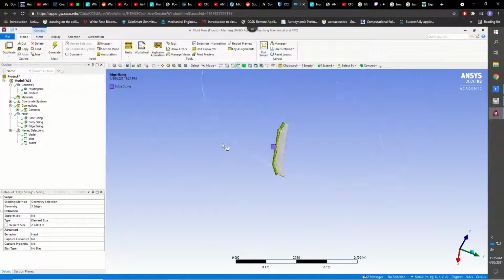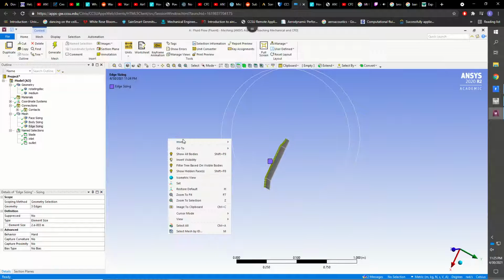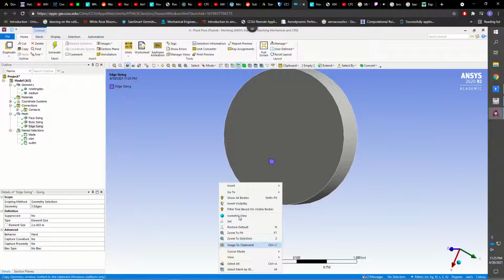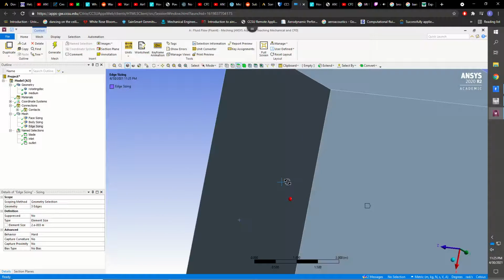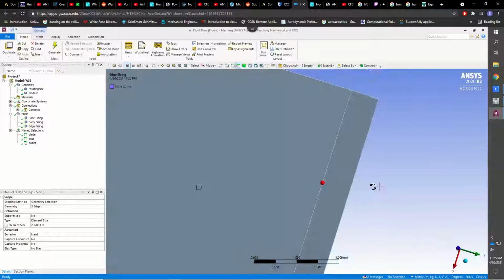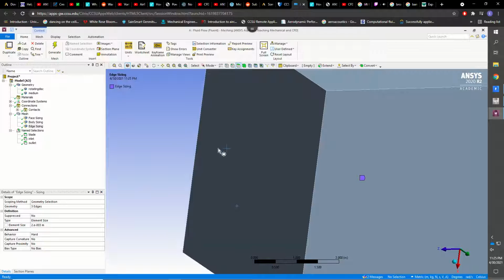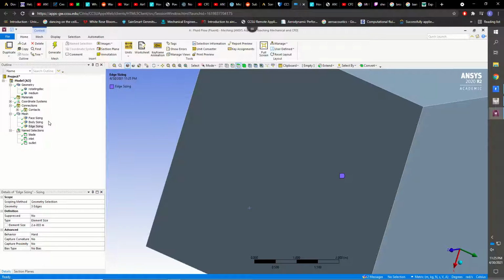And then I put an inlet and outlet. I selected it with this face select on the z-axis, because that's where my blades spin, so I have an inlet and an outlet that I labeled, which will be automatically generated when I go into Fluent to do the setup. So those were my settings for my mesh.